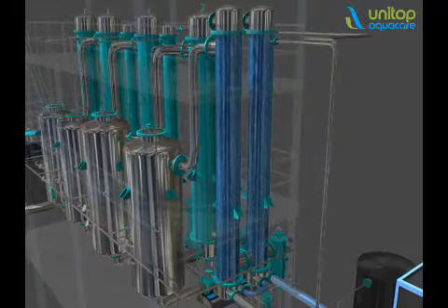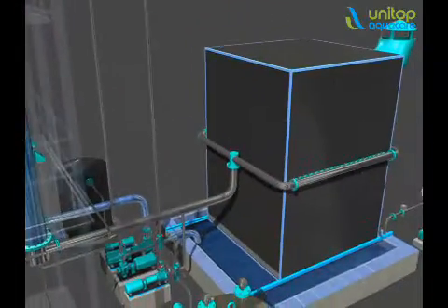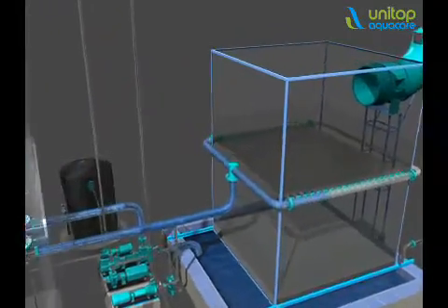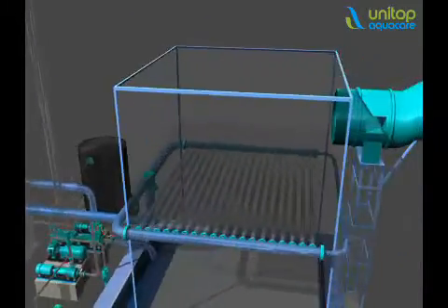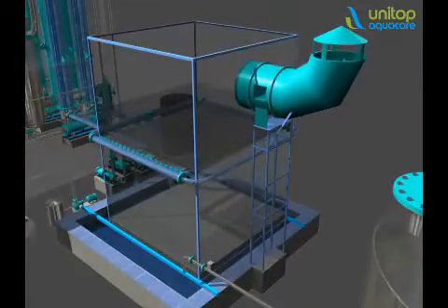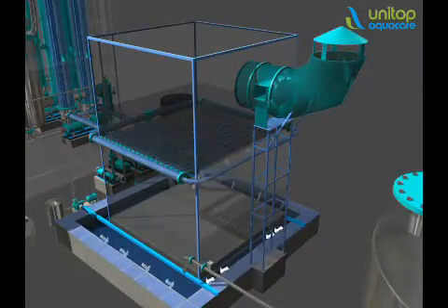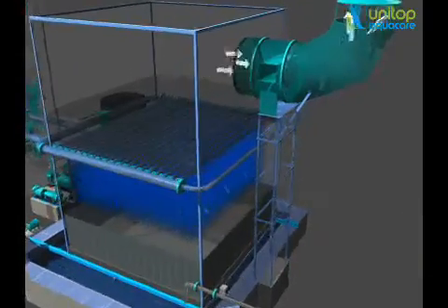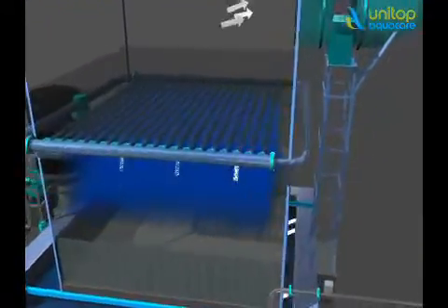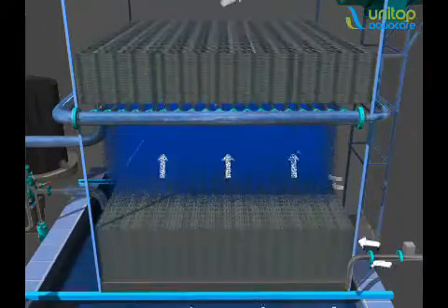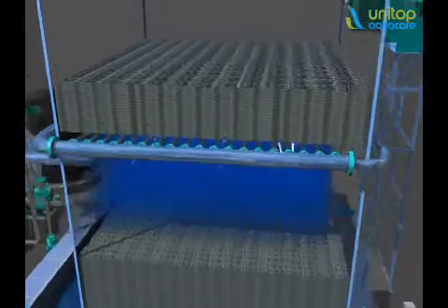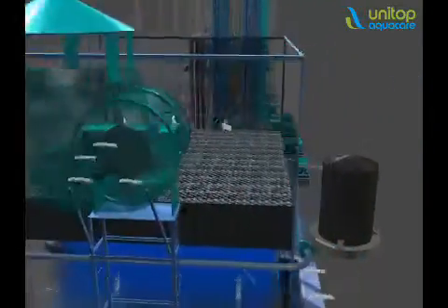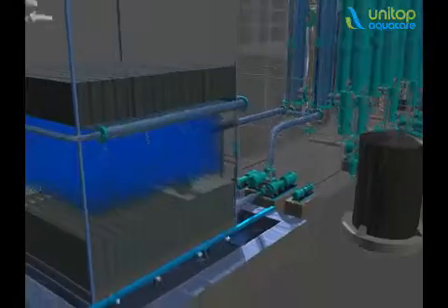the system. During the process, the sensible heat of the liquid is used to evaporate the water in the feed, which comes to you free of cost, saving a lot of steam. The hot liquid is sprayed in the adiabatic evaporator through evaporative fills and gets cooled by the fresh draft of cold air. This method not only saves steam, but also removes the requirement of a cooling tower from the system.